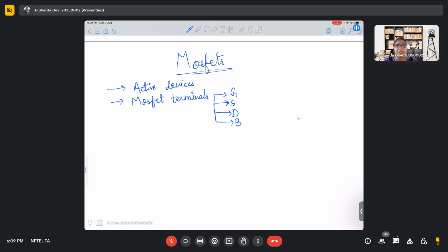that is not physically possible to design a circuit or a chip with all terminals of body shorted with the source of a MOSFET during fabrication. It's a very tedious task, and it takes a lot of routing to short your body with the source for each and every transistor. So when you look at it from a fabrication point of view, it's not always possible to short all your body with source.